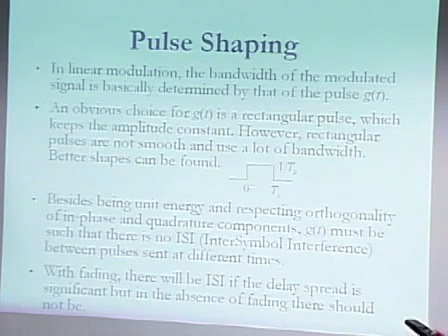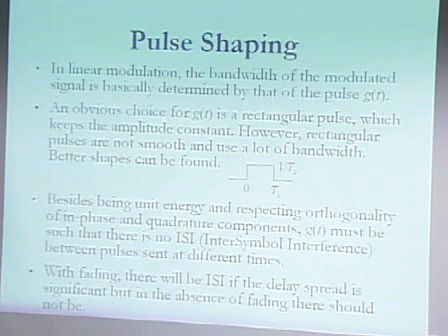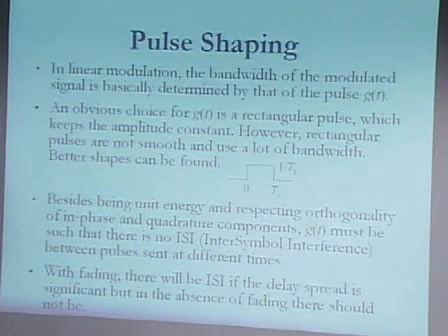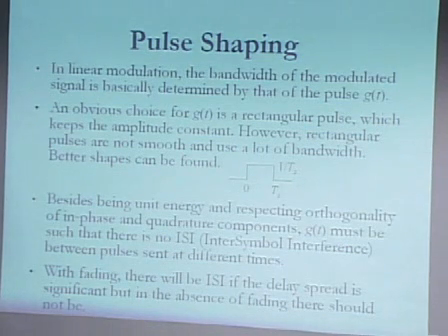The problem is that there's a discontinuity here, right? There is a property of the Fourier transformation that tells you that for a signal to be compact in one domain, it has to be smooth in the other domain. Smooth means being as continuous as possible. In fact, you can prove that if you have a temporal shape like this one, its Fourier transformation falls off in frequency with a decay, so with frequency to some exponent, which is given by the number of derivatives that are continuous in the time domain.